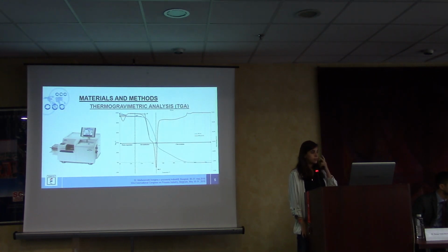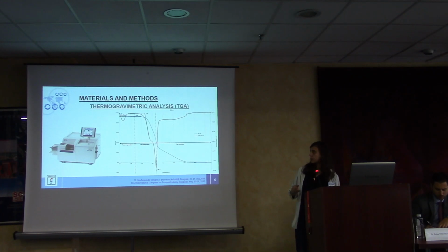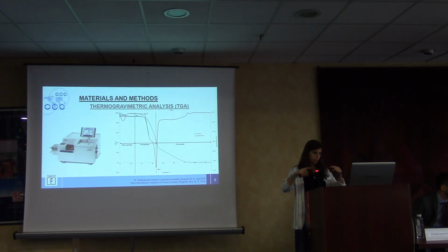For the tests that we have carried out, the first one was the thermogravimetric analysis. Probably you know it, but I'm going to explain it briefly. In this study, we heat a sample at a heating rate, in this case 5 Kelvin per minute, and we measure the weight loss all the time. That allows us to know the induction temperature, which is the temperature at which the reaction of combustion really accelerates, and then the combustion increases.